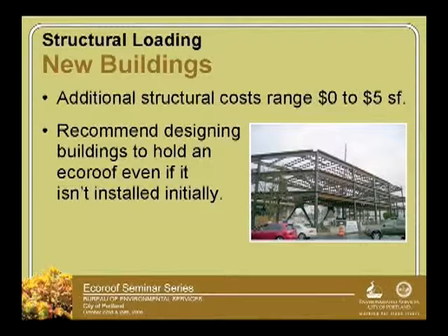What we're thinking is that sometimes, depending on whether it's a wood, steel, or concrete system, that additional structural loading may cost no money because it may have already been designed to hold a gravel ballast roof, or maybe up to $5 a square foot of building footprint for additional loading. But our recommendation, because we'd love to live in this world, is that we just say, hey, just design it for an Ecoroof. If you don't put it on now, let us know, and maybe we'll put it on later in a few years.